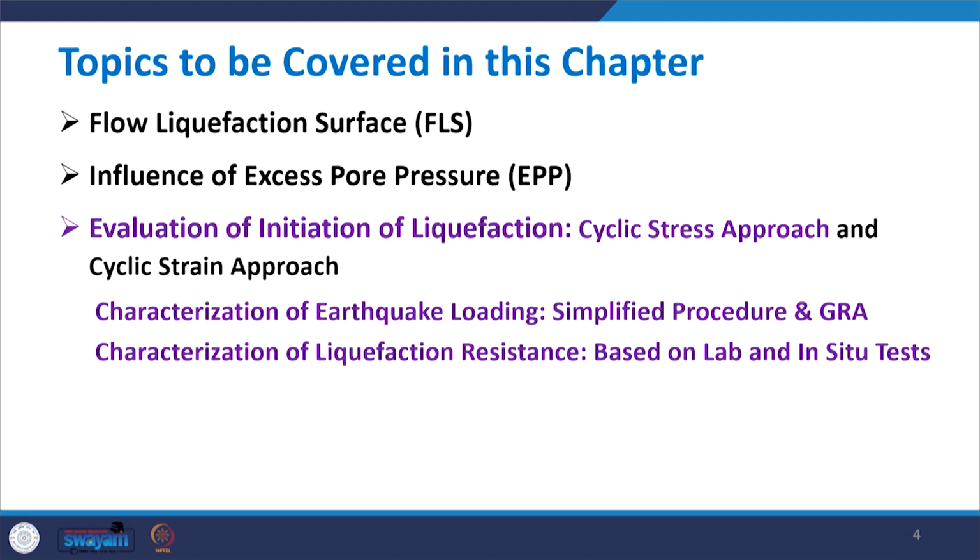In the cyclic stress approach, both are characterized in terms of cyclic shear stresses. Now, coming to the characterization of earthquake loading, it is done by 2 processes: either the simplified procedure or what we call ground response analysis. Similarly, characterization of liquefaction resistance is done based on laboratory or in situ tests.